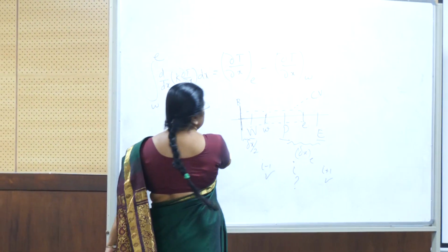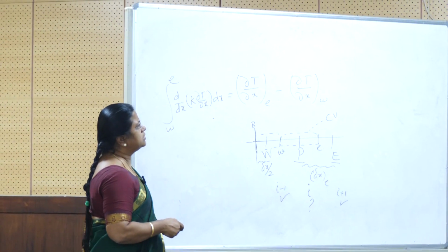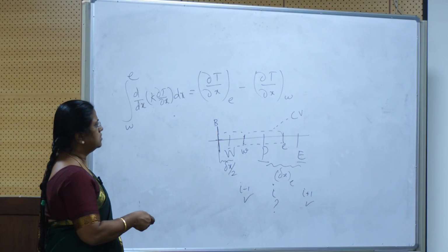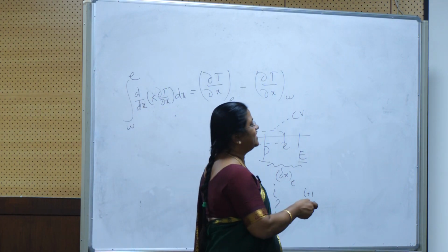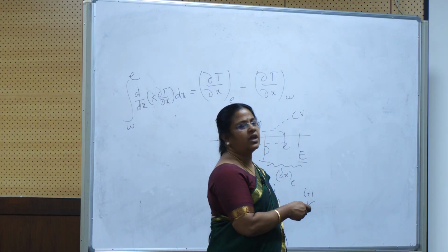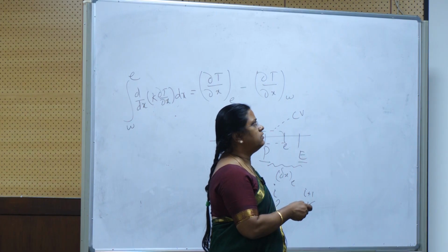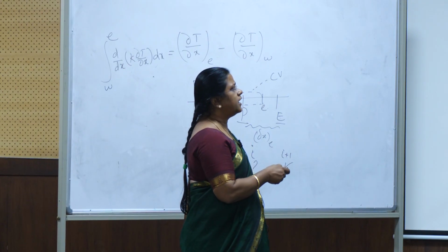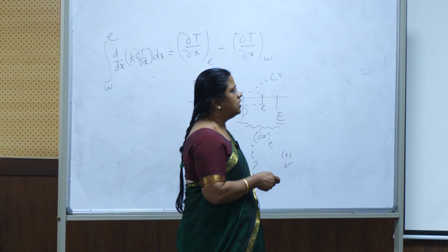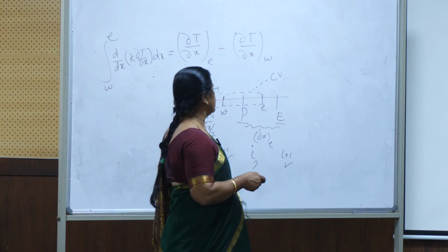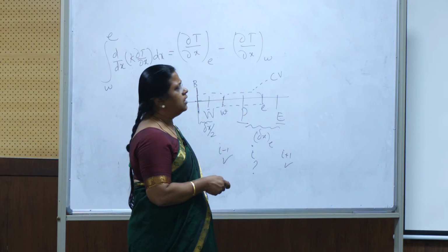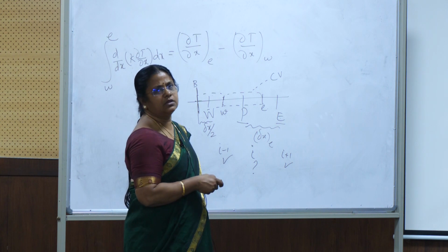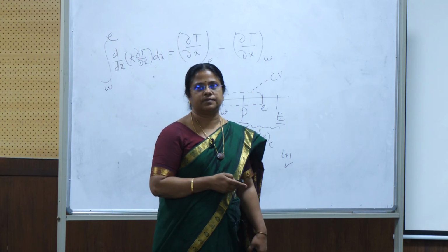Same way, only like this integration. That is why it is written like this. You see there. E minus W: upper one minus the lower value. Same thing, E minus W here. On both sides you will get delta x, one dimensional, and now it gets cancelled out. That is what we saw in the beginning. The same picture here: P is here, W and E, and the control volume is situated in between, and the distance between the nodal points is delta x.